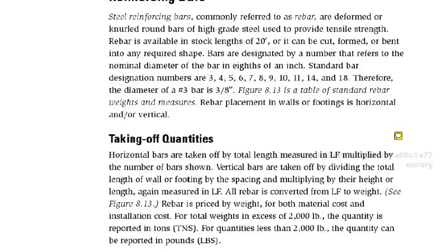And that generally will be specified in the plans, and you shouldn't make substitutions because the size of the bar relates directly to the structural strength and the tensile strength in particular of the finished product. So you don't make substitutions. I don't care how much you have in your yard. You stick to the specifications. Now you can talk to the designer about it if you want, but I don't recommend it. It's generally not worth the time.